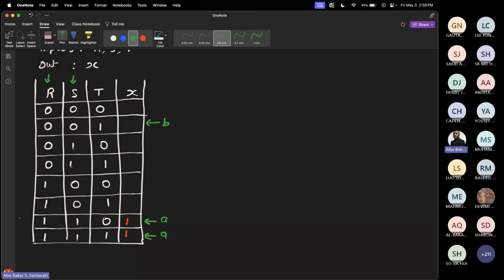Is there another one? Oh, sorry, this is 0, 0, 1. So this is wrong. 0, 1, 1. That's here. So this is condition B. Is there another 0, 1, 1? No. So that means in this section, we should have a 1. And then for the rest, our system X should be off. So we put a 0. We're done with all our conditions.